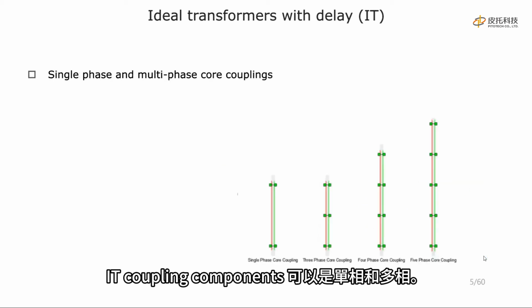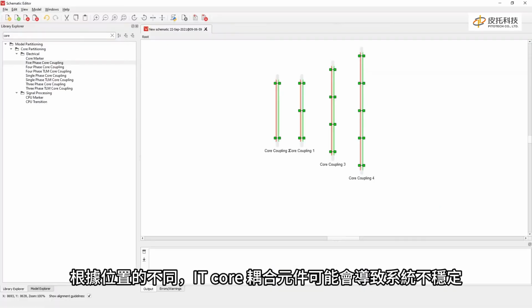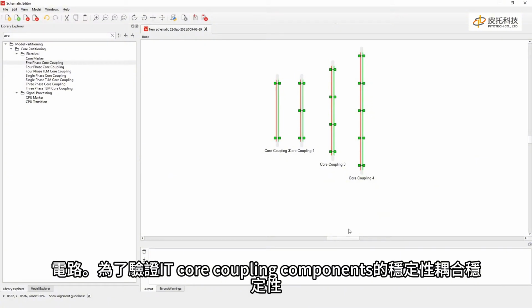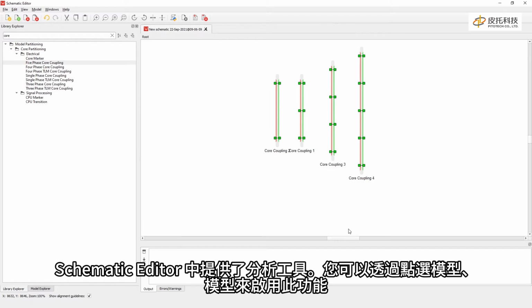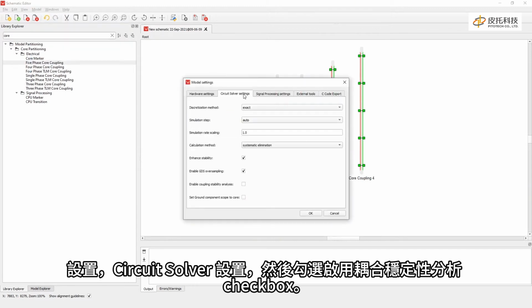IT coupling components can be single-phase and multi-phase. You can find out more details about each type in the documentation link in the Materials tab. Depending on the position, IT core coupling elements can introduce instabilities in the circuit. In order to verify the stability of IT core coupling components, a coupling stability analysis tool is available in Schematic Editor. You can enable this by clicking on Model Settings, Circuit Solver Settings, and then checking the Enable Coupling Stability Analysis checkbox.